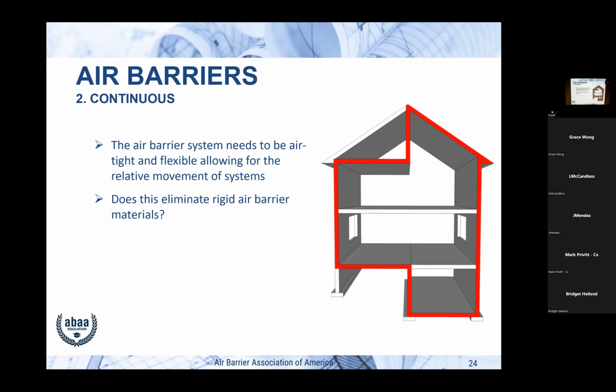Okay, so you see this on one side, you got what I would call a roof with a ventilated attic. The other side, we have a cathedral ceiling, which is not ventilated. But you need to trace on your building, and then down into the bottom, you have one where there's a foundation, a basement, that's conditioned space, and then you have what could be a carport underneath there. So you've got to understand where your air leakage control layer is.